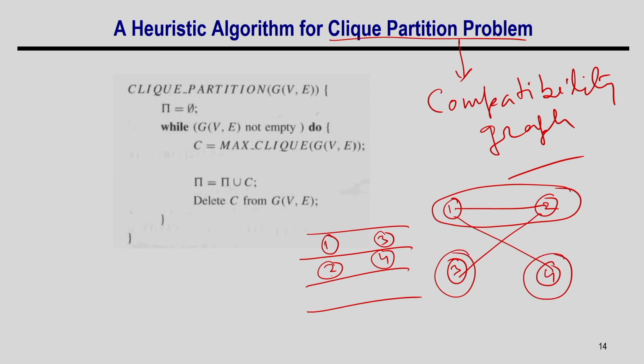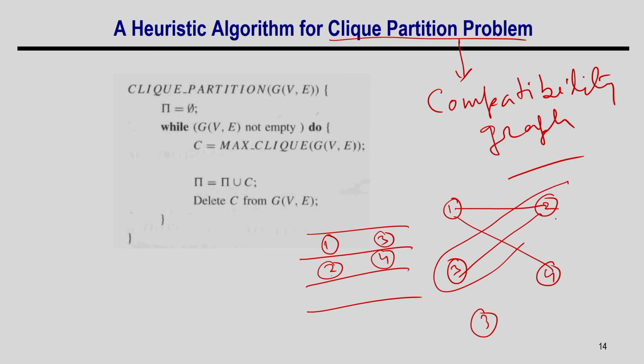If I go this way, I need basically three function units. These are all adders, right. So I need 3 adders. But if I partition this way, say I club these two together and this is the 2 clique, then I need 2 adders. So you can understand that for the same problem, different clique coverage gives you different numbers of units.